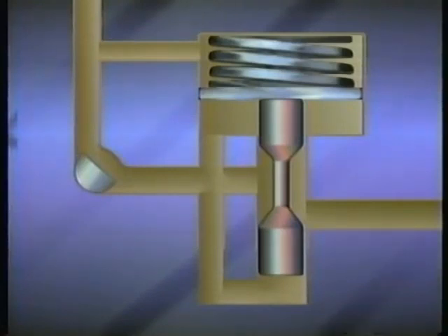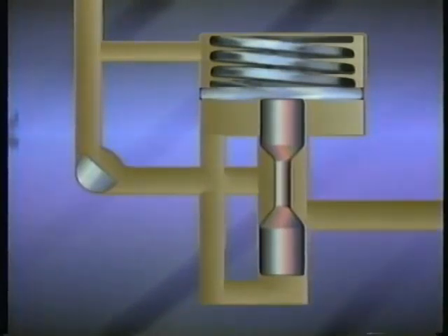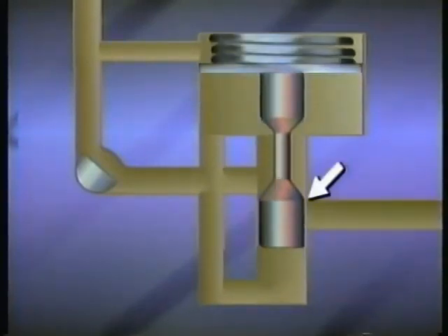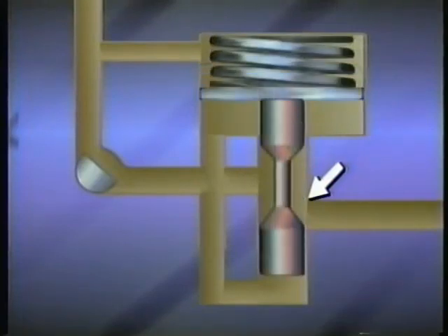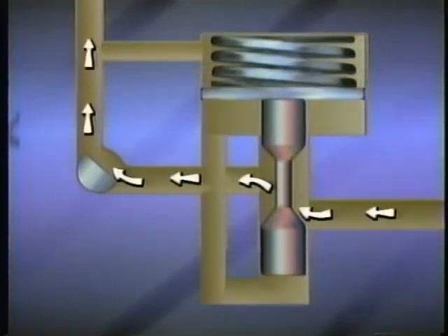Basically, in response to changes in inlet and outlet pressure, the spool can move up to close the inlet, or the spool moves down to open the inlet. This allows only that amount of fluid to enter the valve that can be forced through the throttle. Keep in mind that some flow control valves are better suited for certain applications than others.